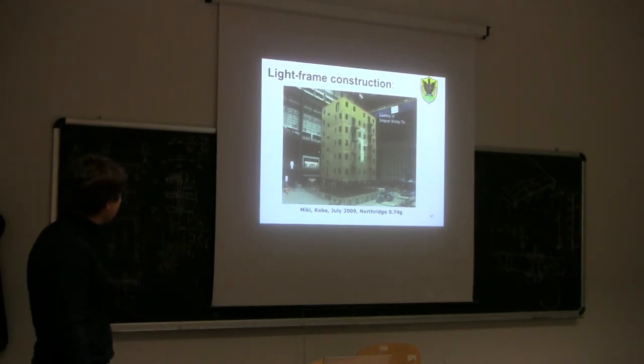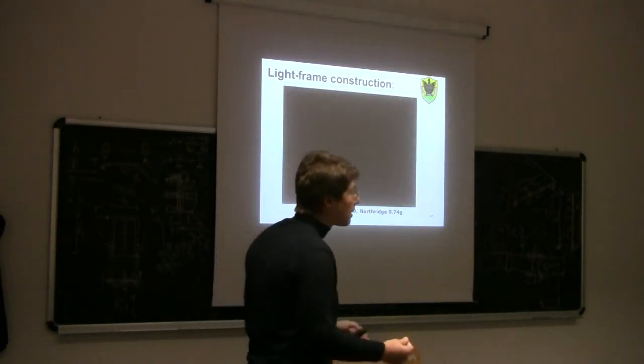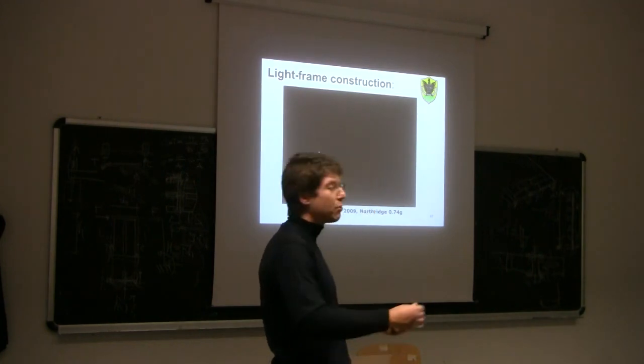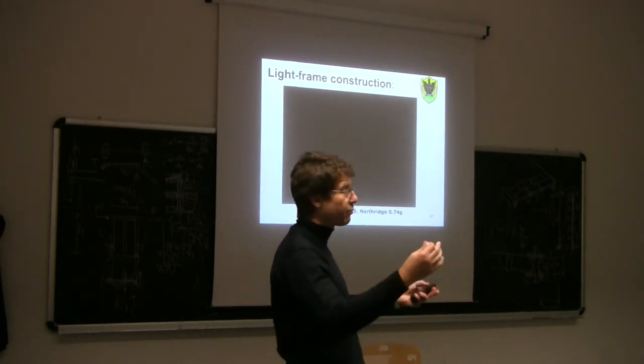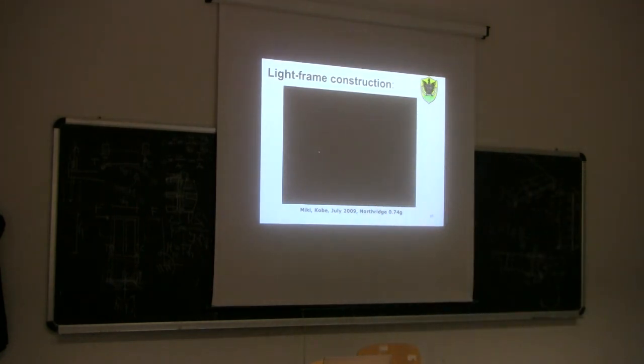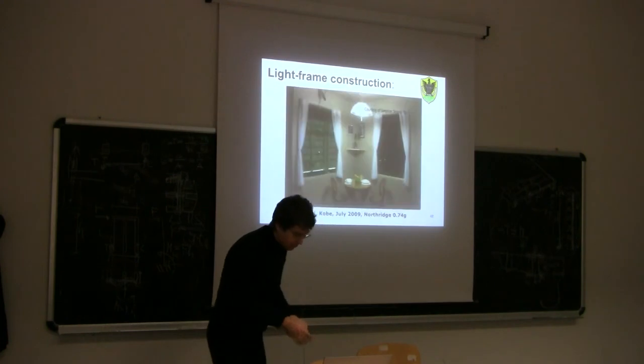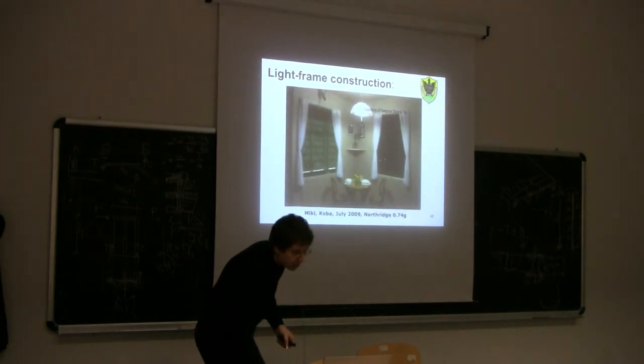Of course, timber structures are very flexible, so you can see there are significant displacements. If during an earthquake you are in a timber building, you will shake a lot. You have to be careful that something doesn't fall down, for example from shelves or something like this. But usually the building doesn't break because it's very elastic, so you don't have significant problems. You can see also from the inside, those videos are taken from the internet.